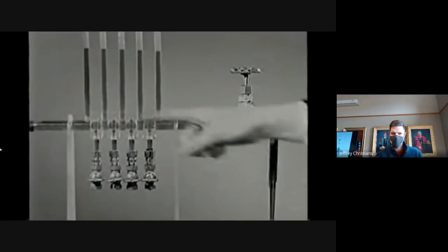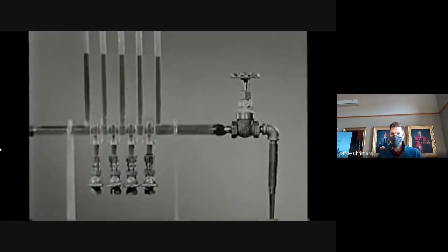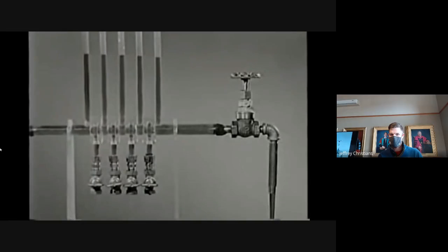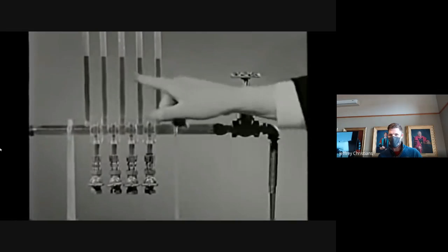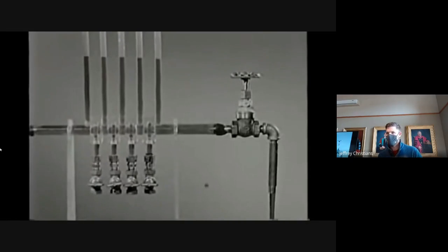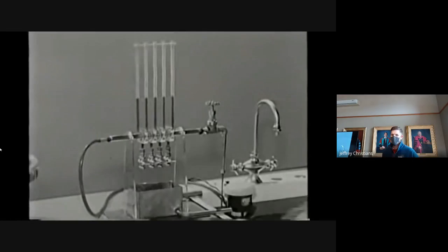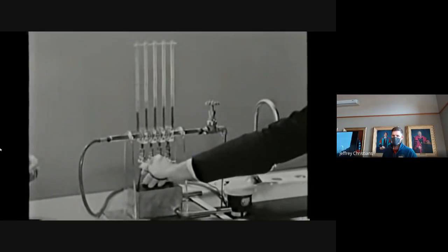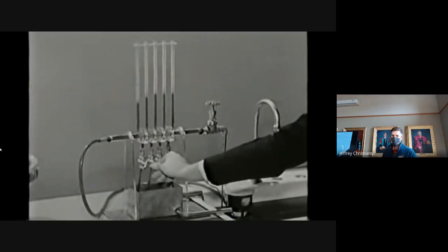It is shown by the water levels in these manometers. With the bleed valves closed, the average water velocity is the same at all cross sections. And there is a very slight pressure drop due to viscous force. Right, you can see the head loss from viscosity. Now we reduce the volume flow at successive sections by bleeding water from the manifold.